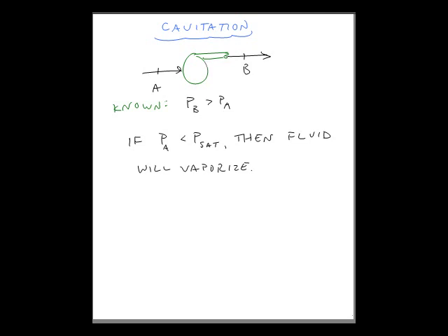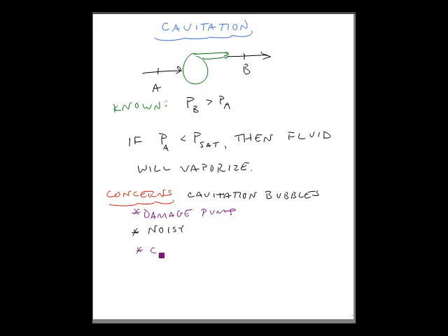So the concerns are that, well, cavitation bubbles. The bubbles caused by cavitation damage the pump, are noisy, and they cause an efficiency drop.